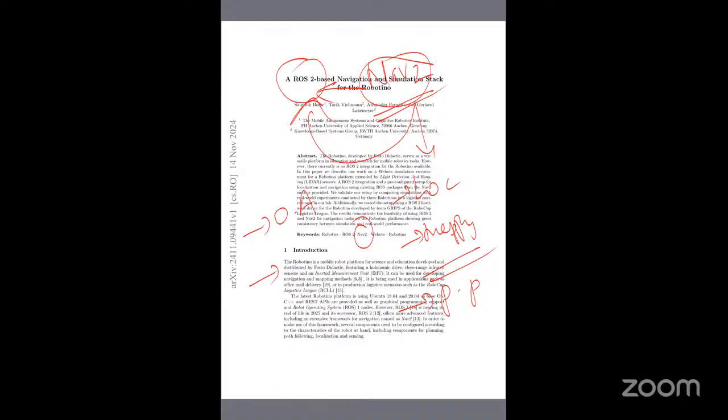Okay, if the robot sees an obstacle, it will go in another path. Then goal navigation. Goal navigation means, suppose now the robot is here, and the goal is to reach point B. This is the point given by the user, right? So there is a goal to reach here. This navigation is what is called goal navigation. So this Nav2 will do all these things: localization, mapping, path planning, obstacle avoidance, and goal navigation.